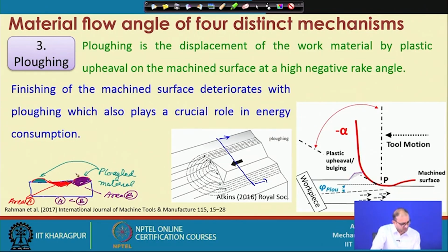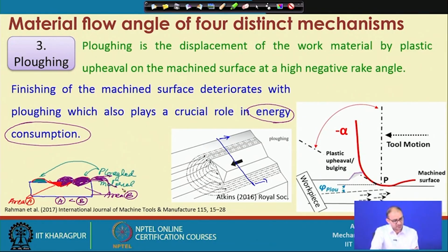So, in the next case your tool may encounter more material, and because of that you have to spend more energy to remove that much material. And it may continue, because whatever you are ending with here, some of the material will pile up here again, even though some material is removed here. It may fall down in this particular area also, and if you extend this workpiece then some material will be here also, and that is again called the plowed material.